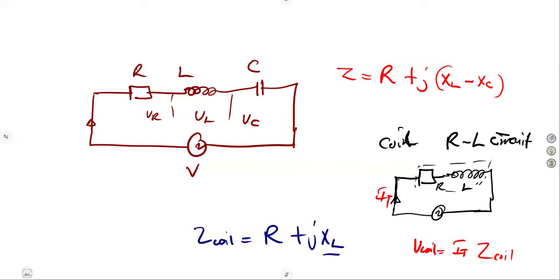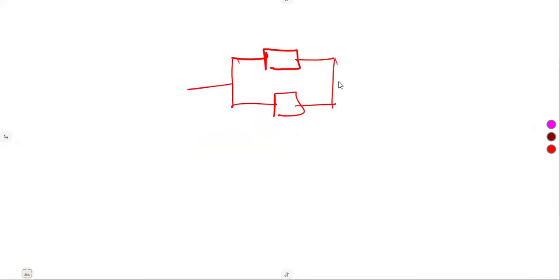So do revise, guys. Go through normal combinations of impedances when an impedance is taken into consideration in parallel. This is an impedance, this is an impedance. For us to find the total impedance in parallel, product over sum.